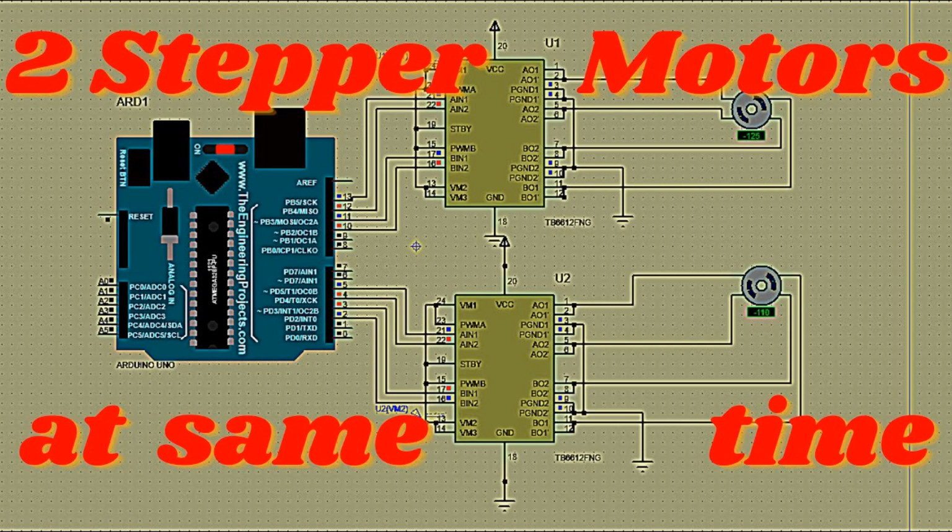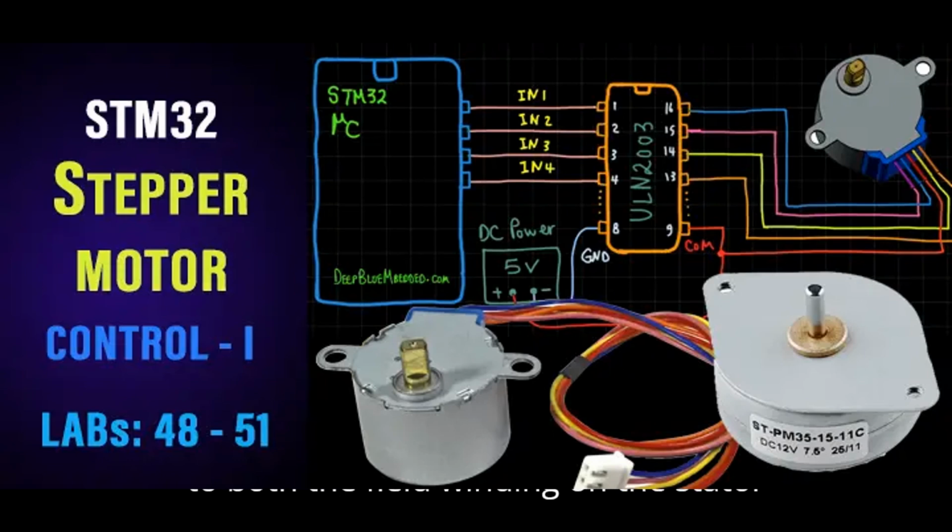Overcurrent protection. The driver protects the motor by sensing excessive current and shutting down the motor if necessary to prevent damage. Soft start/stop. Drivers can provide a smooth start and stop to reduce mechanical shock and prevent damage to the motor and connected load. 2. Basic operation of universal motor drivers. Universal motors typically operate by applying a voltage to both the field winding on the stator and the armature on the rotor. The driver modulates this voltage to control motor operation.